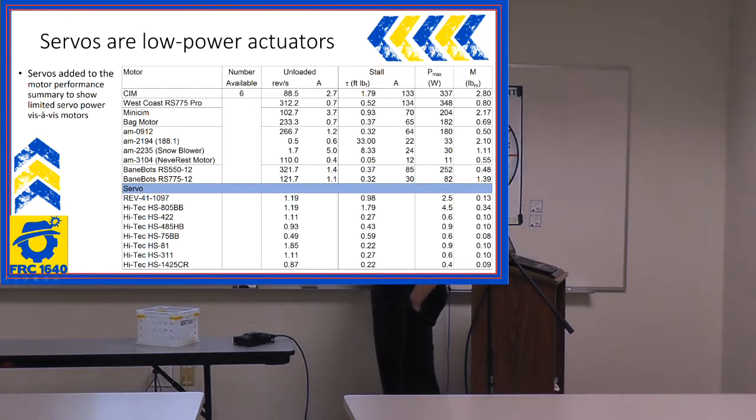But we do have a couple that are okay. The 4.5, that's that big honking servo that we use for the gears, and we also are using it for the angle adjustment. At 4.5 watts, it's not so bad. These are the smart servos that we're buying from Rev Robotics now. At 2.5 for a small servo, that's really good when you compare it to all of their brothers.